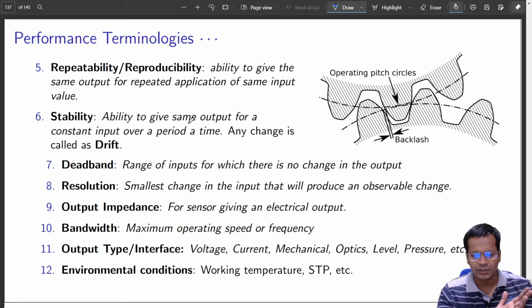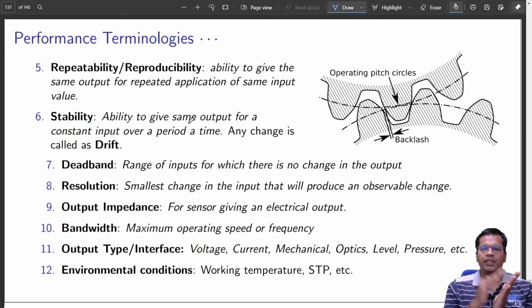Let us say the working temperature varies from 0 to 70 degrees centigrade in the case of industrial sensors. If it is sensing acceleration, then you should know that the voltage corresponding to the acceleration is valid only if the sensor itself is lying at this working temperature.